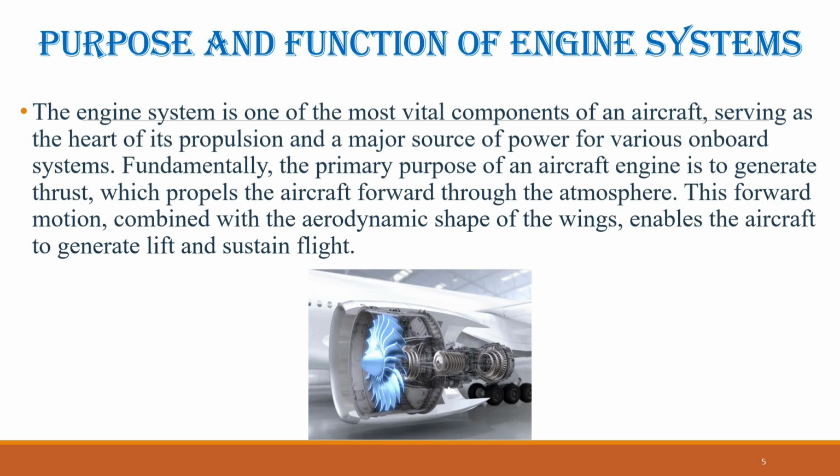Furthermore, high-pressure bleed air extracted from the engine compressor stages is used in environmental control systems, which manage cabin pressurization and temperature regulation. This same bleed air may also be routed to anti-ice systems to prevent the accumulation of ice on wings, engine inlets, and other vital surfaces during flight through icing conditions.